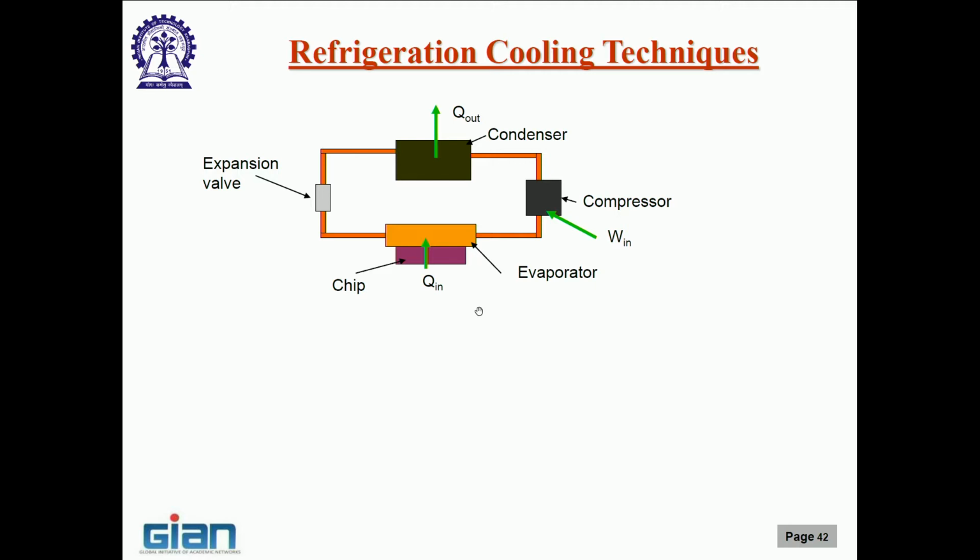So, the heat is actually flowing from the room, which you have probably set at 20 to 25 degrees centigrade, to the outside, where on a typical Kharagpur summer day the temperature can be as high as 45, even 47 I think. So, you are actually extracting heat from a room which is at 25 degrees centigrade and rejecting it to an ambient which is at 45 degrees centigrade. Spontaneously that is not possible, but it is possible because I am doing external mechanical work through this compressor.